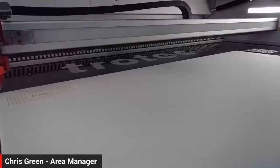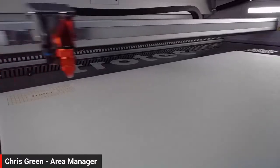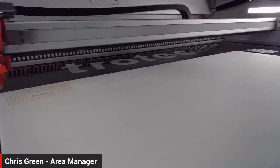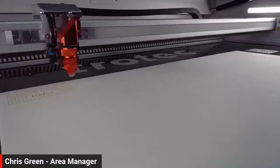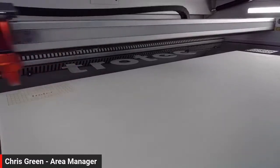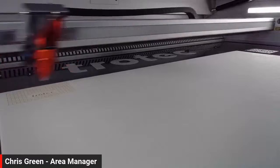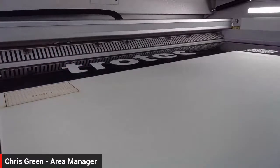With the bed covered off here, the plywood was slightly warped. The extraction that we've cut out here, just to reiterate on extraction, is holding the plywood down, pulling it down, so we get a perfectly flat face when we engrave. If we didn't have the extraction covered off, the plywood would be slightly warped, being a wood product. This is one of the things we have to deal with. But again, we can never underestimate extraction.